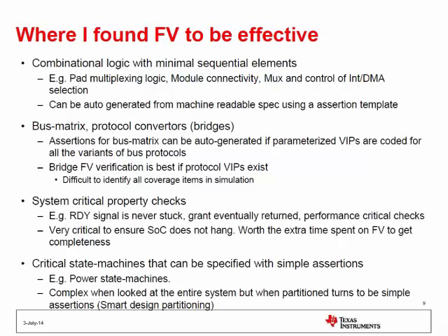And there may be certain other cases also like this, like if you're having a cache controller or some kind of protocol conversion between a memory and your CPU, if you're having a huge amount of prefetch buffers and things like that, there again you may want to apply these checks for hang and critical state machines. I found it very useful, and again, as I said, if you are able to convince yourself this is a critical module, you'll be able to get buy-in from your management to spend the extra amount of time that you need, because this is like a make-or-break feature.